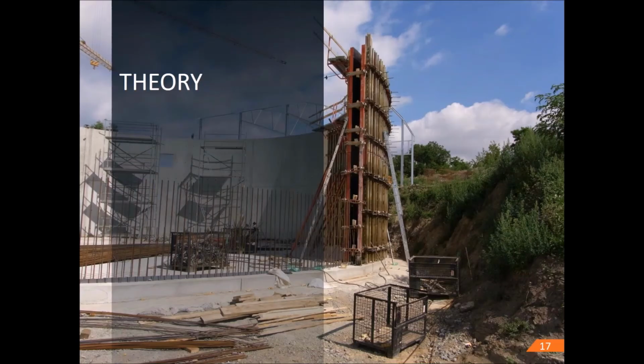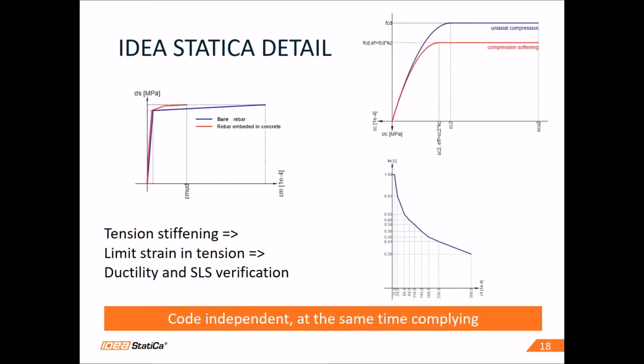A little bit of theory, what's implemented in the software. As we said, it's a code-independent method, but at the same time, it complies to the code because we use the material diagrams or stress-strain relationships which are provided by it.